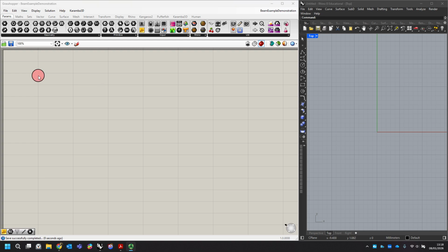Okay, so I've got my Grasshopper canvas open. I've also got the Rhino canvas beside it. Something that a few of you might remember from first year is that it's useful to be able to visualize what you're doing, but it can quickly get a bit cluttered if you're looking in the Rhino canvas at everything. So it's normal to click here, and what that should do is only preview the geometry for selected objects that we're interested in.